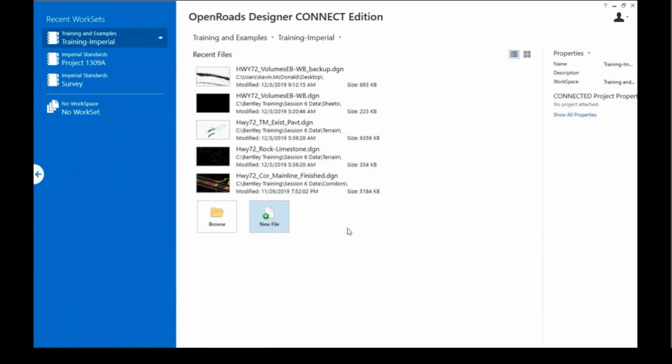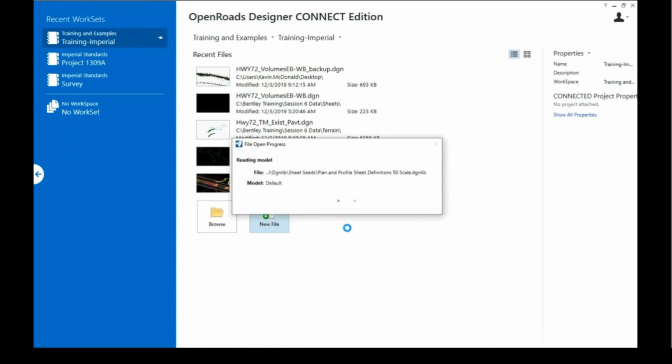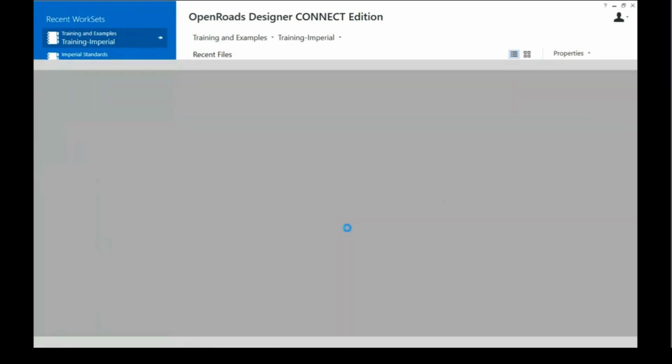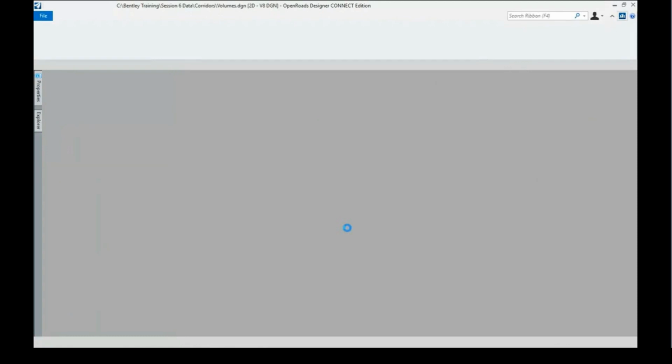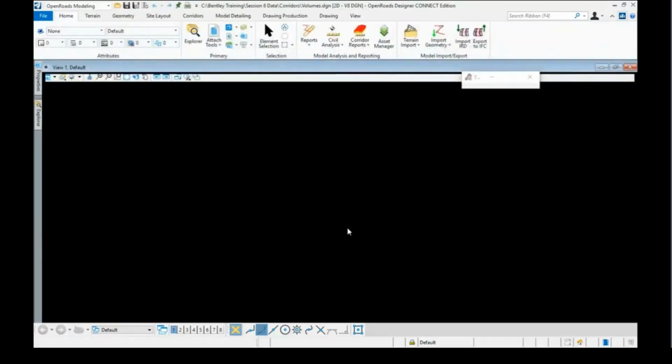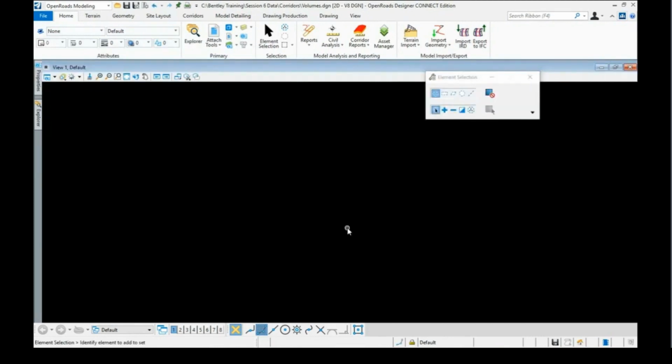Over the past 4 weeks, Joey and Scott have been doing all the hard work on the design here. They've created the horizontal and vertical on our project. They ran the corridor modeler and created the basis of the corridor. Then they came in the next week and did the intersection design and a median crossover design, and last week Scott did the bridge abutment design. So the design that's taken place to this point has been a mix of corridor modeling, linear templates, and surface templates all on the slope. All that has been done here.